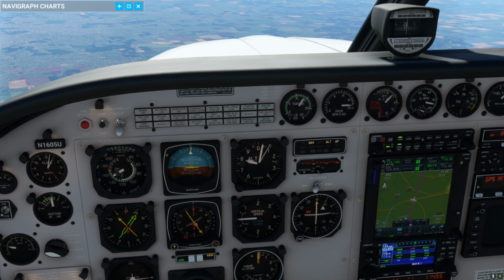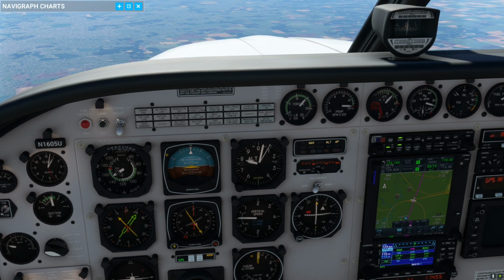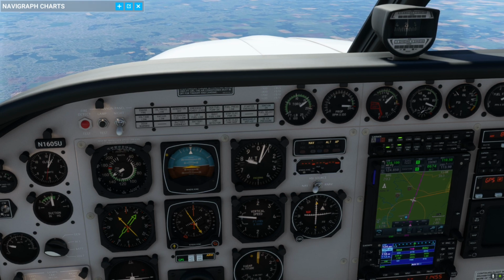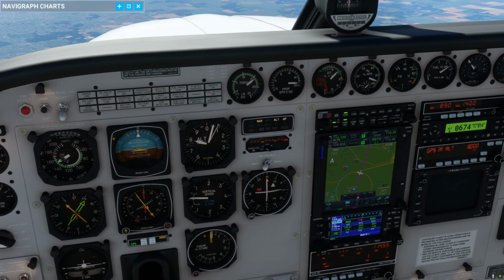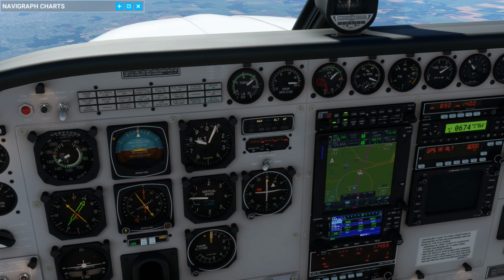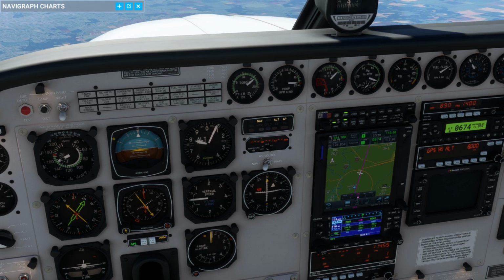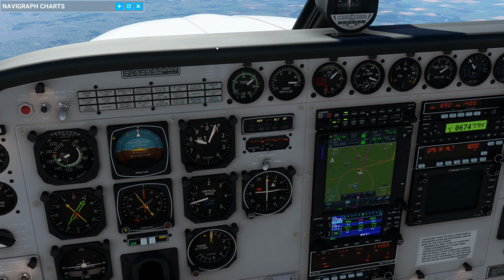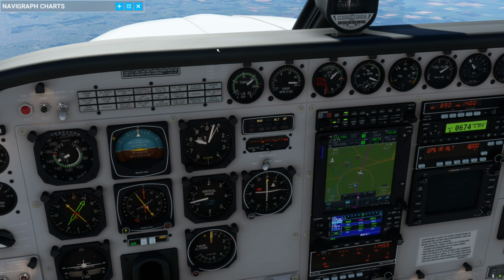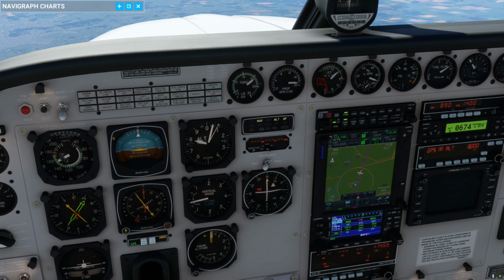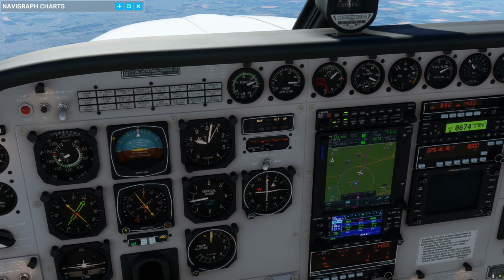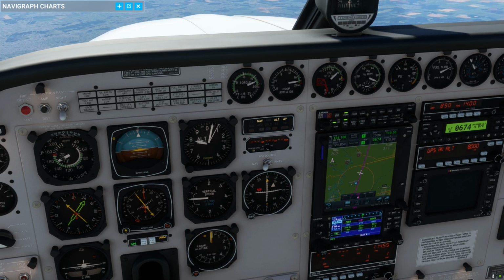Alright, so it's cruise settings, which are 17, I think. It's been a while since I've flown this thing. Should probably pull up my notes. Regular cruise, that's not helpful. 1700 to 1750. All right, so 1700 torque. Bring this down to 1750 on the props.